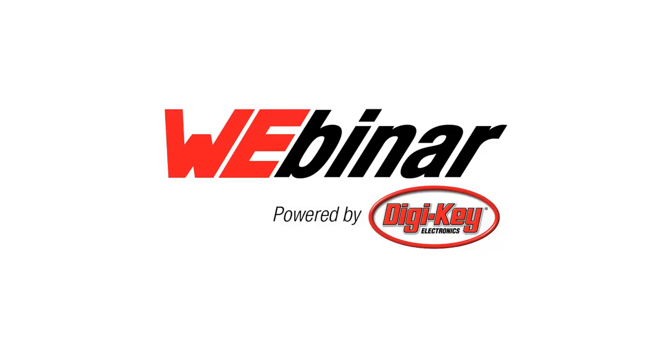Our next question: do the crystal data sheets typically have the crystal in isolation measurements? It would be helpful if it were on the data sheet so we could skip the step of pulling the crystal off of the PCB to make that measurement. So you're asking about those values, the C0, the C1, the R1, the L1, that make up the motional and the holder arm of the crystal equivalent circuit, and why don't we put those on the data sheet? Well, they're not normally on the data sheet. Honestly, the reason is that if I put it on a data sheet, I then have to meet it. If I have to meet it in production, then that really limits stuff. And you saw that ESR, the resistance, where I tried to explain how it had a Gaussian distribution with a few parts that have a big outlier on it, yeah?